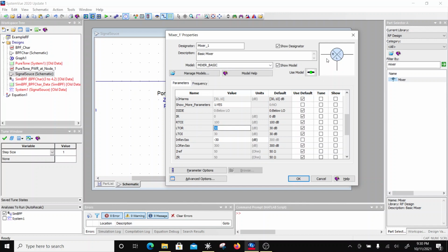On the receiver side, this isolation is going to be bad because RF would be separated from LO by 11 megahertz, right? When it comes to direct conversion, it becomes much worse because in that case, RF and LO are the same frequencies. So you understand what that number is, right? You can put a large number here, because the frequencies are differing a lot. You can put 40-50 dB isolation here, okay?